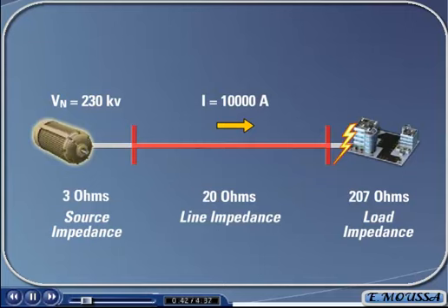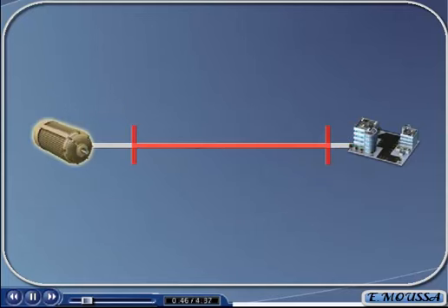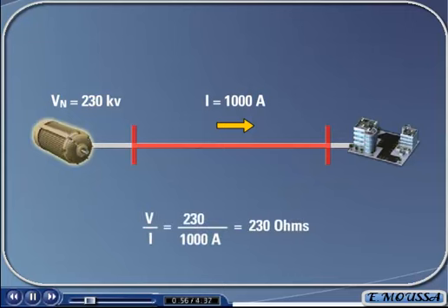The operating principle of distance protection for transmission lines works in the following way. The magnitude of current and voltage is measured at the beginning of the transmission line, and using these measurements calculates a ratio of the voltage over the current. This ratio will then give you a value that is equal to the impedance of the total power system.